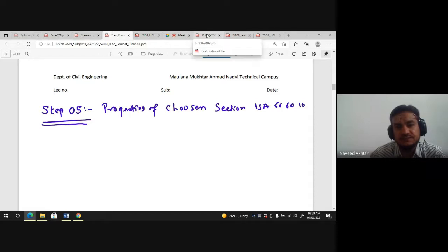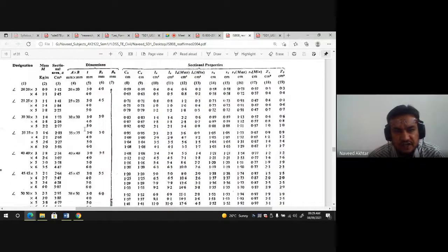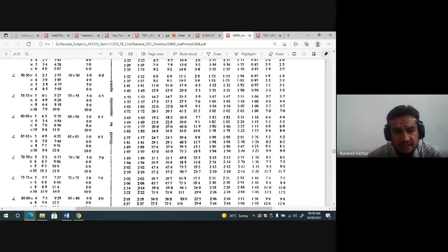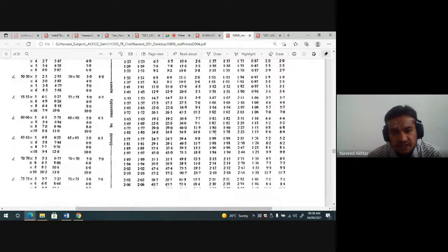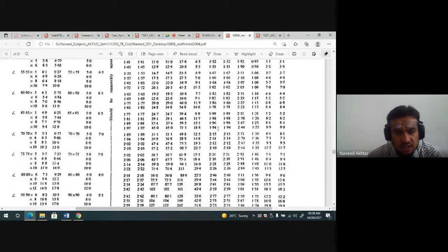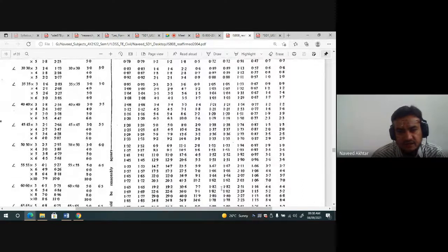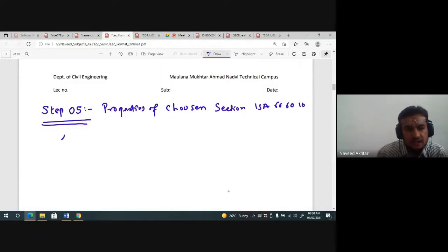Okay, so if you come here, ISA 60/60/10, this one, the radius of gyration is given in RXX and columns 14 and 15. I will come here. So for 60/60/10, the radius of gyration is 19.4 mm. Okay, so RXX or RYY both are 19.4 mm. Sorry, 16.8 mm. I will write down R minimum, RXX, is nothing but RZZ, 17.8 mm.